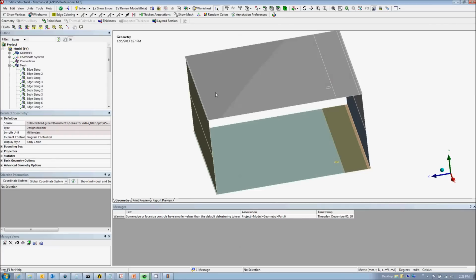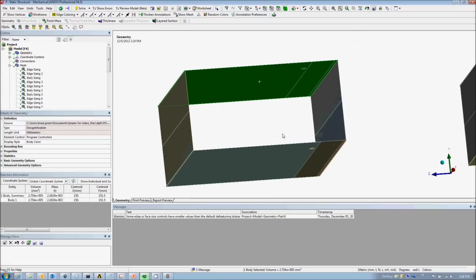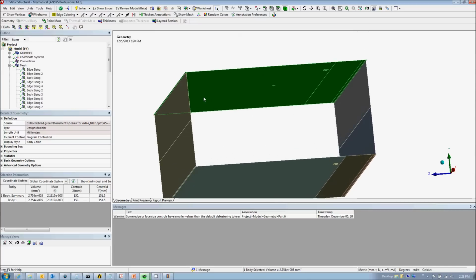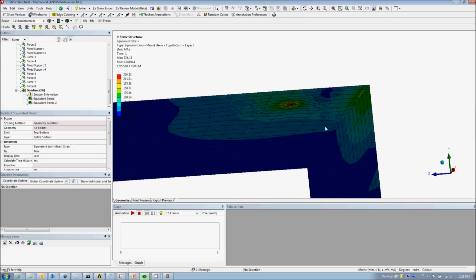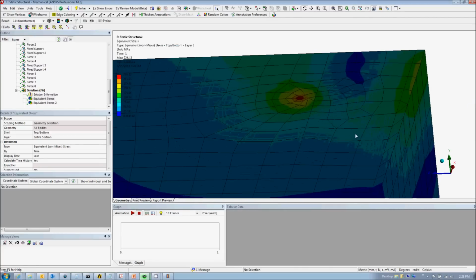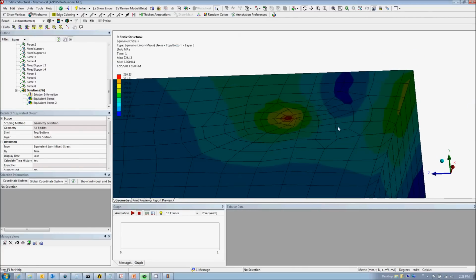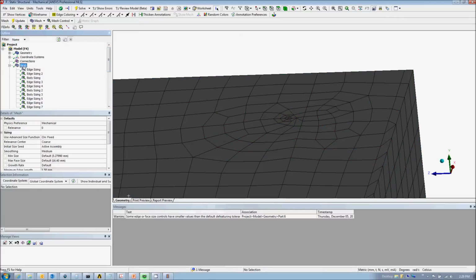However, we'll be focusing only on the top half that has the continuous body instead of dealing with the hybrid of averaged and unaveraged results on the bottom half. In this results view, with the mesh shown, we can visually check for misshapen elements or undesired elements. Here you can see several quad elements that are far from square, and several tri-elements have been included in the mesh where the mesher was not able to create quad elements.